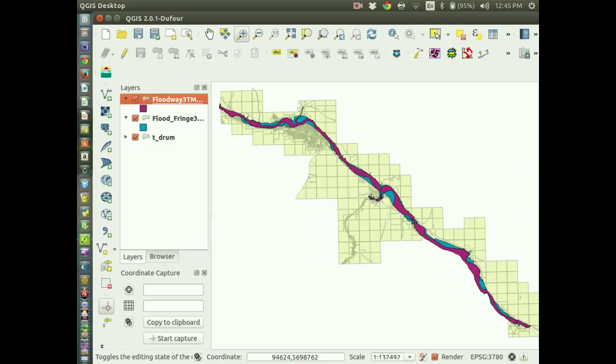So if it has a PRJ and it's got a different coordinate system, it won't ask you, but still you might not know. It will on the fly project it. In fact, if you already have a PRJ, it's even more tricky because you don't know. You don't know until you try to process some overlays or buffering. Or if you're merging.